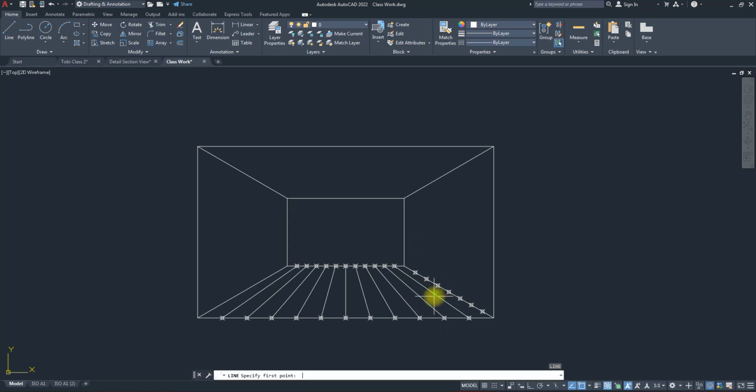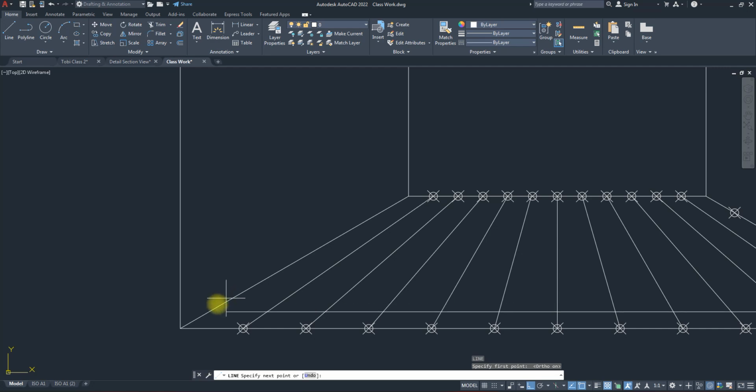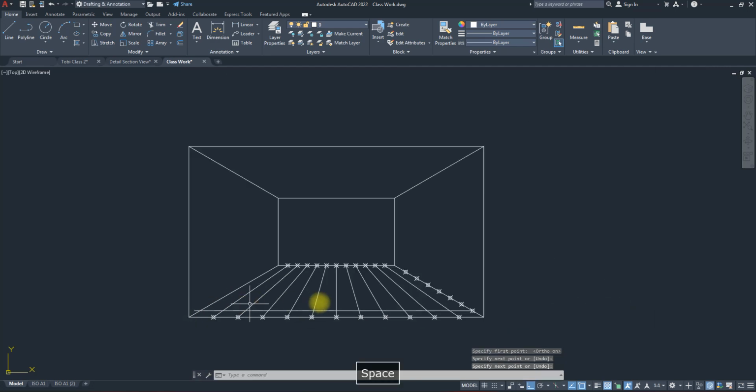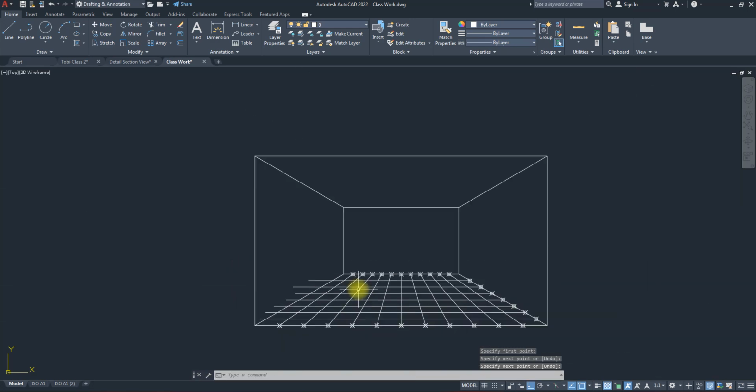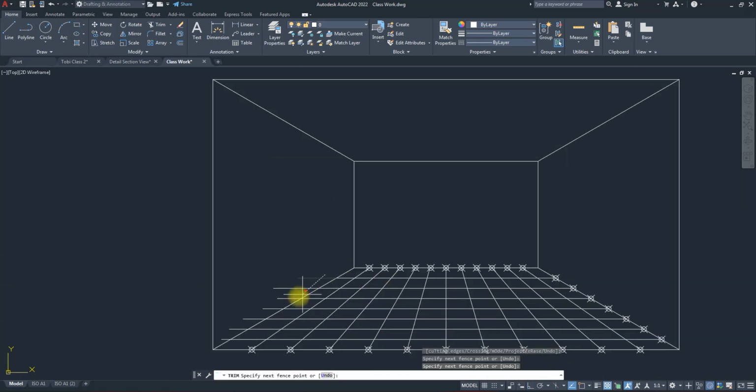Okay, then we can just create a line, make sure our auto mode is on. So create a line all the way. So that we do not miss our mark, we just let it go past a little bit. We'll trim later. Hit spacebar. I think 8 is too small, but let's just continue. So we'll do this. And we keep going. Do we get what I'm doing? Okay. Okay, so we have that. Then I can now use my trim command to get rid of these.